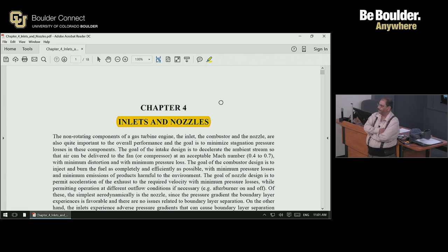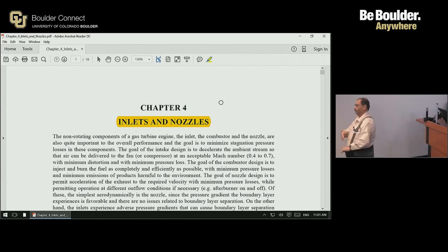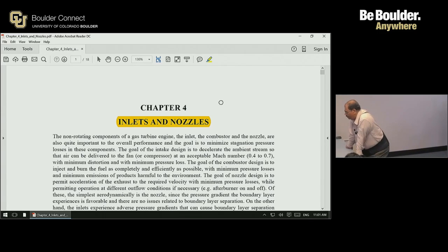Yeah? So I researched the turbine temperature, found it was a bit higher than mine. And increasing that helped? Yeah, that helps. 1,000 degrees Kelvin was probably an underestimate for SU-25, because 1,000 degrees Kelvin was appropriate to sort of a Whittle engine type at that era.